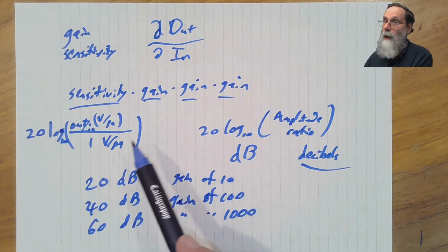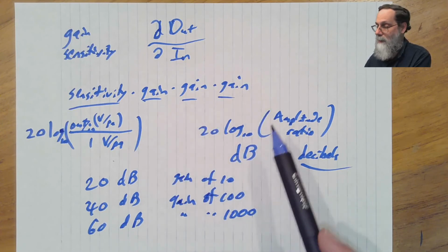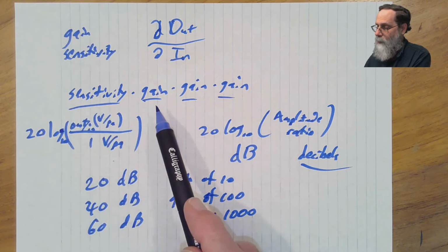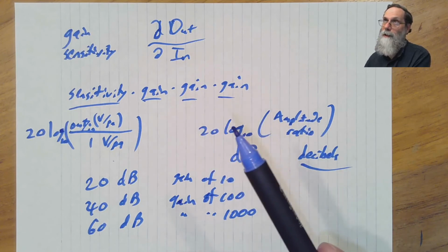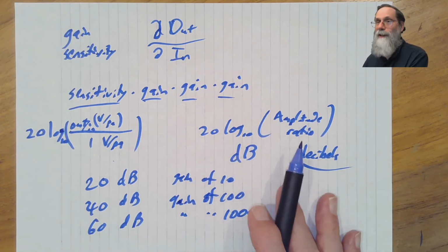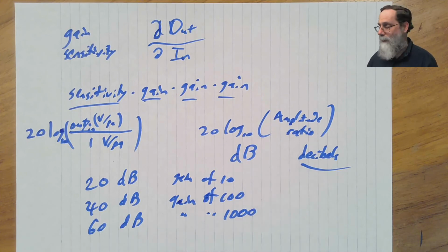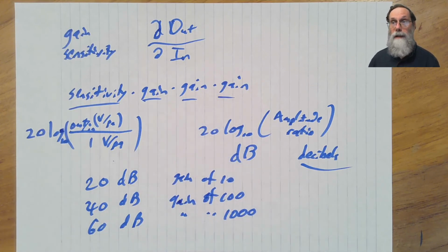And then if I do 20 dB in the first stage, 20 dB in the next stage, and 20 dB in the third stage, you can say minus 47 plus 20 plus 20 plus 20. 60 minus 47 is 13, so I've got a total sensitivity of 13 dB, and I can do that addition in my head, even if the numbers are not nice round numbers. Multiplying things that aren't round numbers is much harder to do in your head. So engineers have gotten into the habit of expressing a lot of things like gain and sensitivity in terms of decibels.